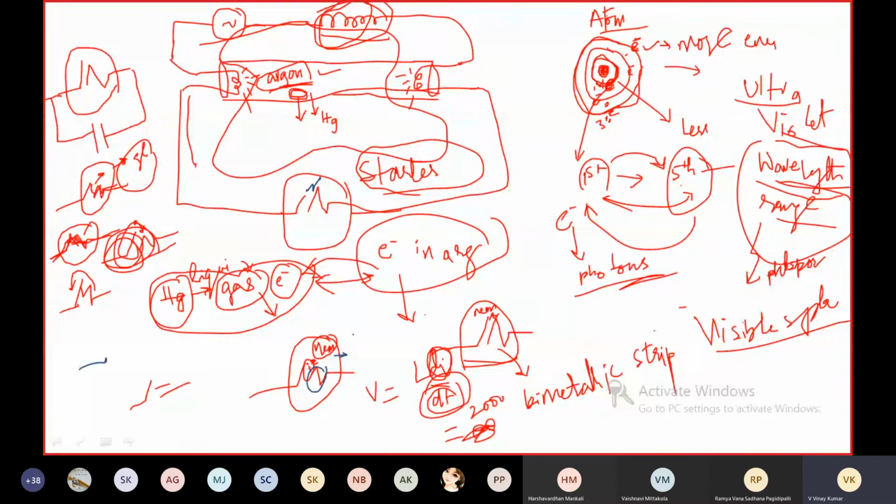See, when these two are in contact, current will be flowing through the circuit. So a magnetic field will be developed in this choke coil. When you open the switch suddenly, due to sudden collapsing of the magnetic field, a large amount of voltage will be produced across this inductor.